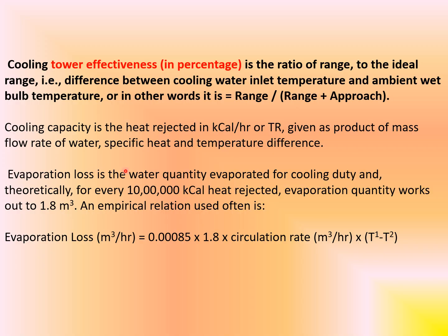Evaporation loss is the water quantity evaporated for cooling duty, and theoretically for every 10 lakh kilocalorie heat rejected, the evaporation quantity works out to be 1.8 cubic meter.